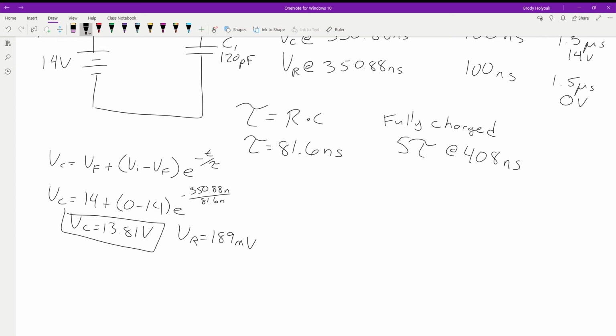What you're hearing is a 60 hertz. That's that little tick every so often. If you time it, it's about a second. A lot of times when we're doing stuff in lab, you're going to get a weird signal that comes in. Most of the time, if you zoom in, it's going to be 60 hertz. What these power supplies do is filter out 60 hertz.